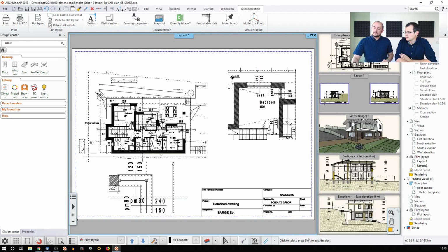I see there that we have a question about how we can do the detailing and other things like that. You can actually make at any time a copy of the dynamic content, which is the original section, which was auto-generated, and it keeps the link with the original building parts. You can select that, make a copy, and paste it into a 2D view.